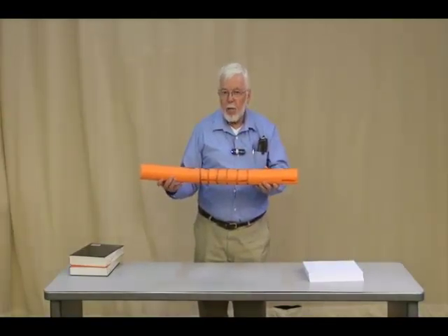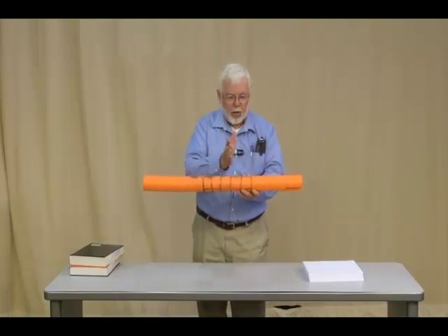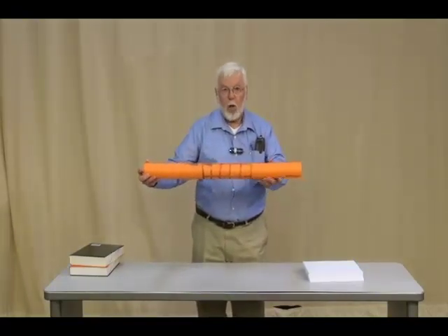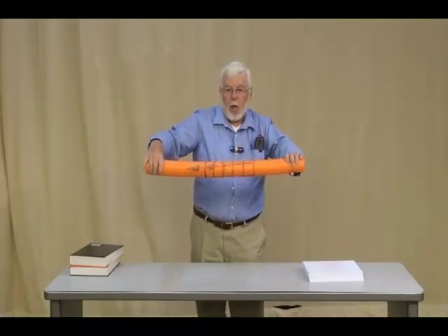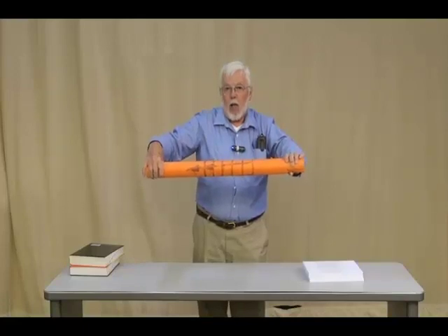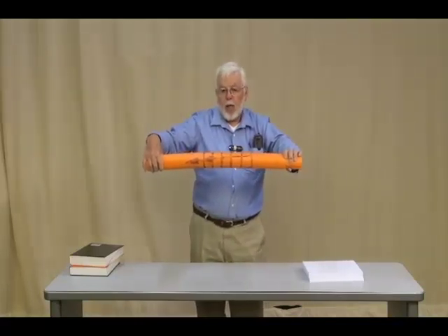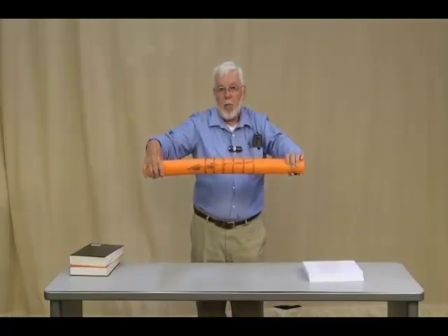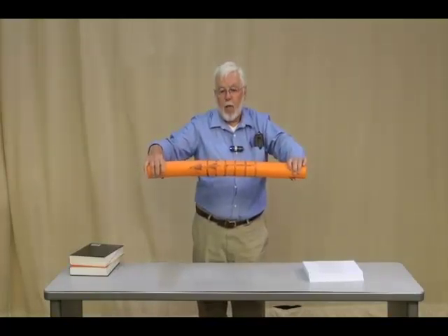So to understand what's happening inside the material, one way to think of it is to imagine this made of a series of slices, perhaps like a piece of bologna with a bunch of bologna slices in it. And let's assume those bologna slices are able to slip on one another as I twist this. And the torque that I'm applying is going to cause those slices to slide on one another, and that's the torsional shear stress, so-called. Now that will be maximal at the outside surface and 0 at the center, and it will be the same magnitude at any given radius all the way around the circumference. So it's like a fan.